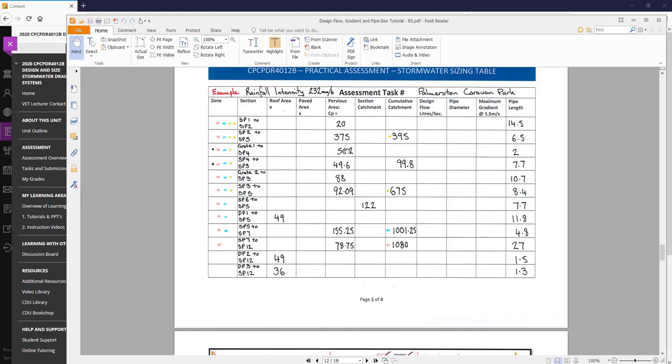You can work out a variation to that later if you want to, but as I say, it's a tropical area, and in Palmerston the runoff is minimal. Now the other thing I've done, I've colour coded down the side here so I know which pipes go together. And see the orange, SP1 to SP2 and SP2 to SP3. That's how I know that that's where I put a cumulative total there. The same here with what goes into this one. It's just these two here, so that's what the black dots are.